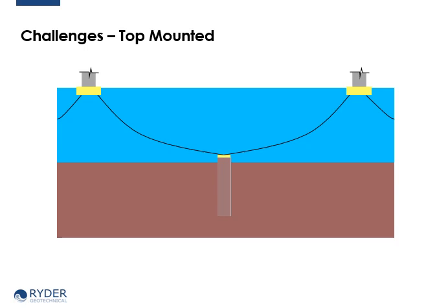And as mooring piles are installed, the soil becomes trapped within the void of the pile, creating heave at the top of the pile, and therefore the pile head comes to rest at a height above seabed. This may cause some disruption of the hydrodynamic flows around the pile, and therefore scour can become a risk.